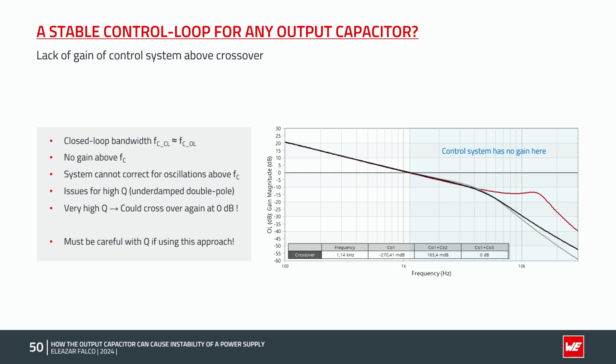So this approach makes the control system very robust against variations not only in the output capacitors, but also in the power inductor. But as seen, this comes at the cost of a worse transient performance, and the best results will be achieved with a redesign of the previous Type 3 compensator.